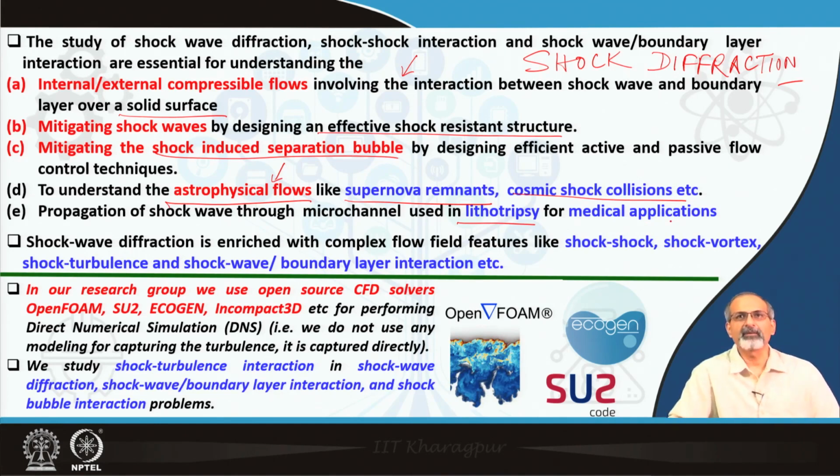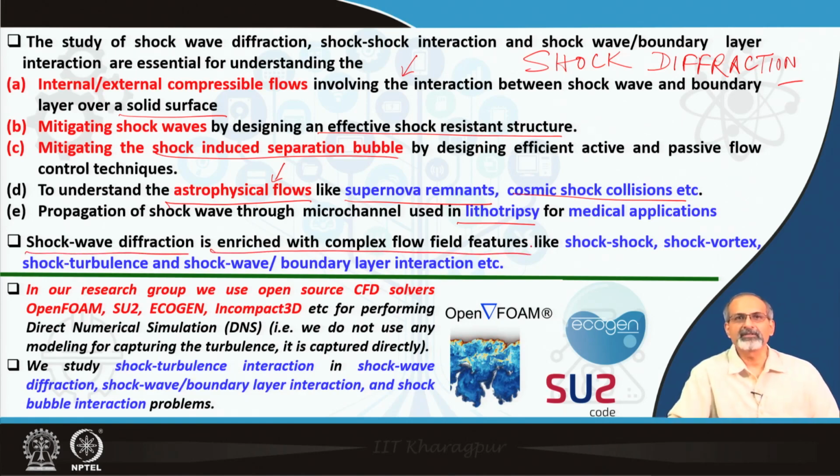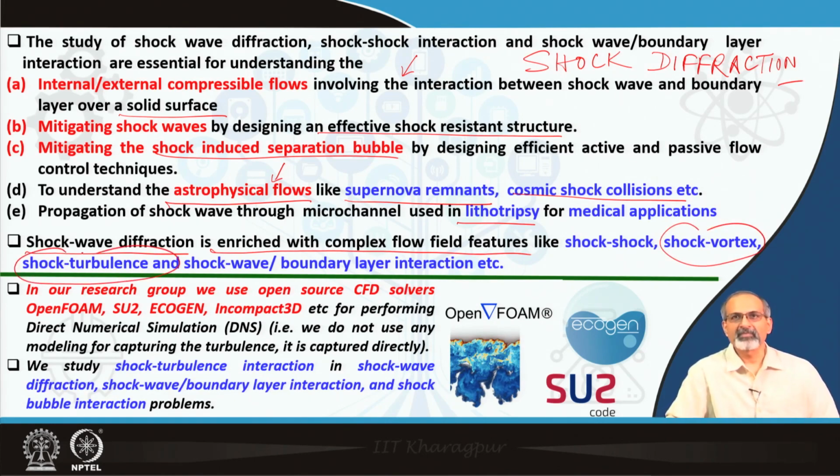All these kind of applications that we are talking about definitely contain shock diffraction, shock interaction, shock wave boundary layer interaction, all these kind of phenomena. And shock wave diffraction is very rich in complex flow field features involving these kind of interactions, additionally shock vortex, shock turbulence, and therefore, it is worth looking at it.